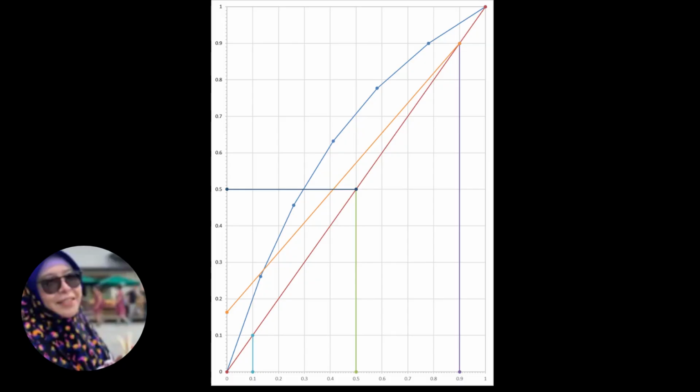For this question, when you want to use the McCabe-Thiele graphical method, what you need is to label the XB, the XF, and the XD. XB is the mole fraction of the bottom product, XF is the mole fraction of the feed, and XD is the mole fraction of the distillate.